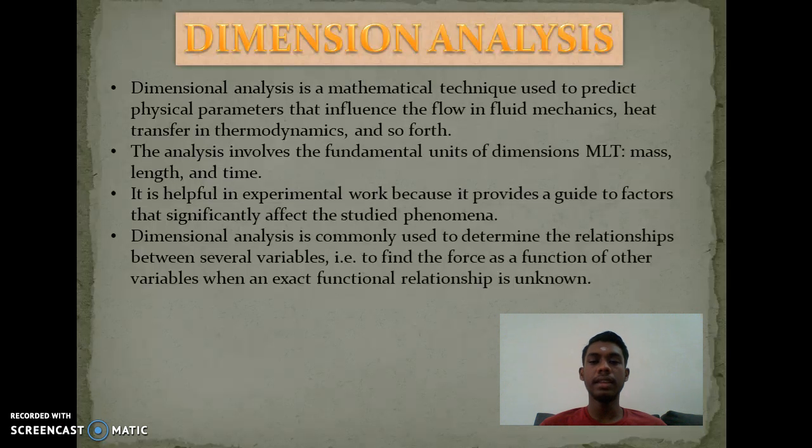Next, we're going to enter dimensional analysis. Dimensional analysis is the mathematical technique used to predict physical parameters that influence the flow in fluid mechanics, heat transfer in thermodynamics, and so forth. The analysis involves the fundamental units of dimension, MLT, which is mass, length, and time. It is helpful in experimental work because it provides a guide to factors that significantly affect the studied phenomena.